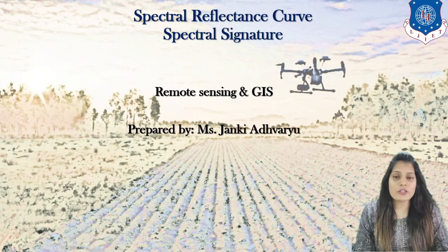Before starting, I would like to give you an example. If I have a vegetation image from a satellite, and the vegetation is very dense, dense meaning more growth of vegetation, how can I make it out? In remote sensing, vegetation is always indicated as red color in a satellite image. When the red color is very dark, it is said to be dense. So you can make out that it is reflected more in the near infrared range. That is why it appears as a very dark red color, right?